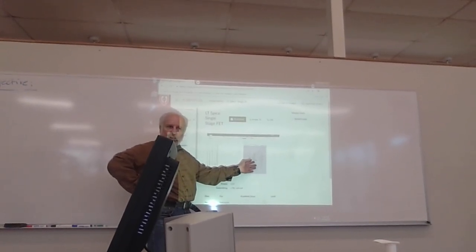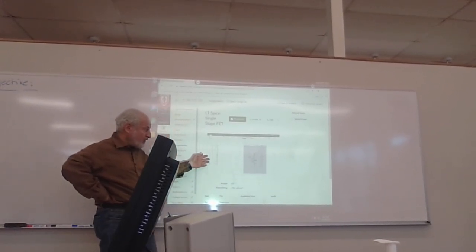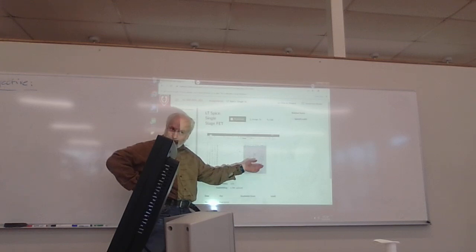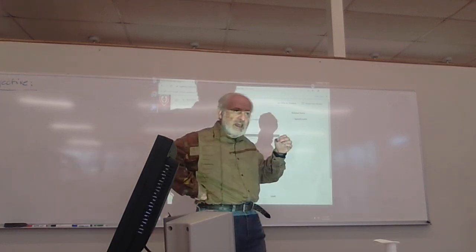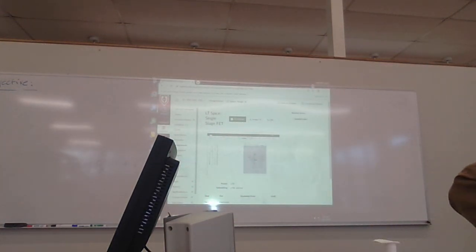Just to quickly show you what's going on. So the JFET circuit is here. I have a table here that changes a value for a specific resistor to change VGS. Does that make sense? By controlling VGS, I am controlling ID. Remember, this is a voltage-controlled device.